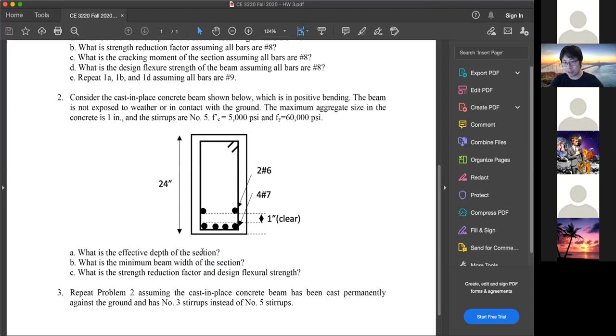If your number is bigger than the textbook A5, we need to see what's going on. But you pick the biggest number, either your solution or the table A5, the larger number dominates, and round up to an integer. There's no half inch in the beam width. If it's like 12.5, make it 13, and so on.